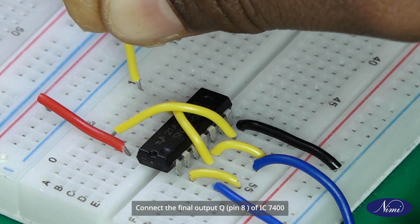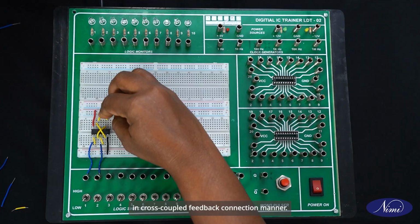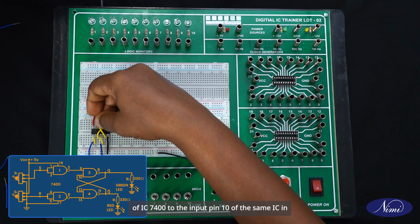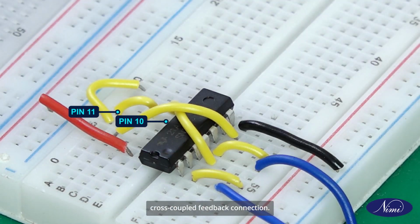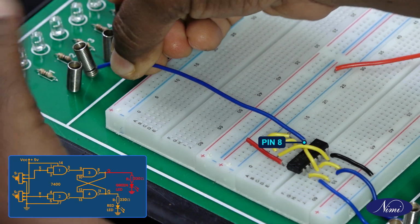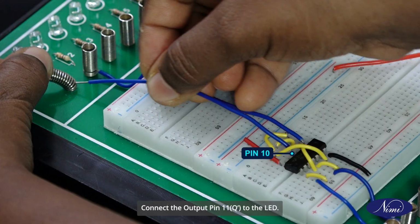Connect the final output Q, pin number 8 of IC 7400 to the input pin 12 of IC 7400 in cross-couple feedback connection manner. Also connect the final output Q bar, pin number 11 of IC 7400 to the input pin 10 of the same IC in cross-couple feedback connection. Connect the output pin 8, Q, to the LED. Connect the output pin 11, Q bar, to the LED.